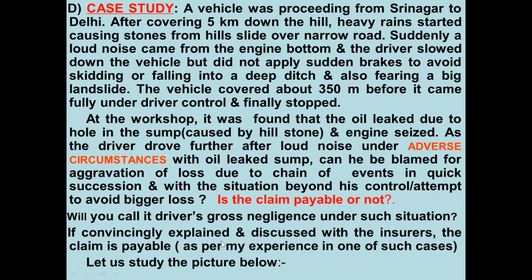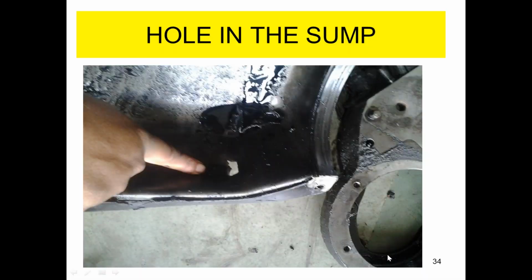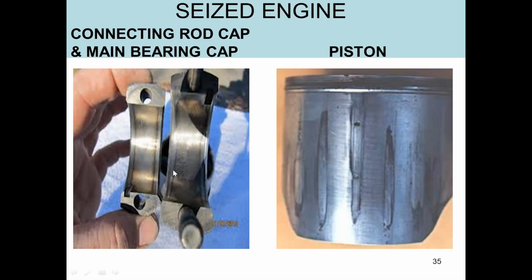If convincingly explained and discussed with the insurers, the claim is payable, as per my experience in one such case. Let us study the picture below. Here is the hole in the sump. Here is the seized engine with the pistons, and this is a big end. This is the main bearing cap. This is the big end bearing cap, and you see the red mark here, that of overheating.